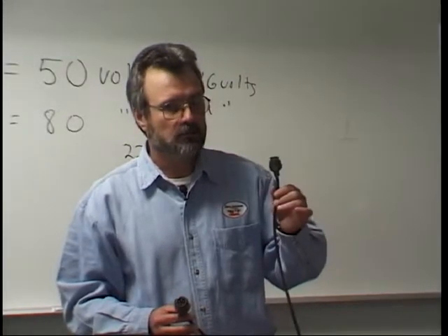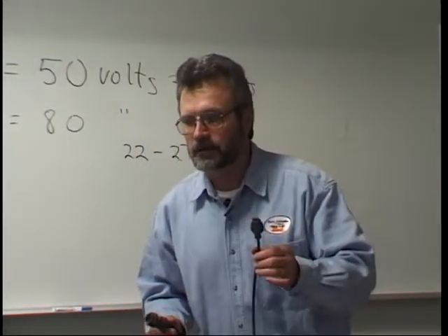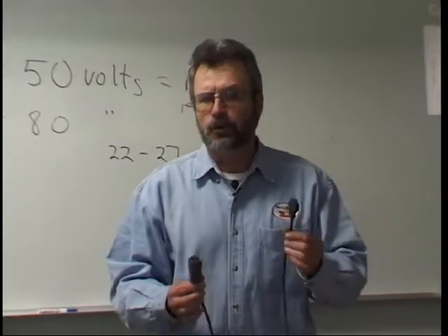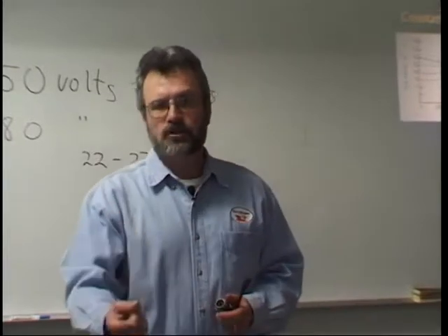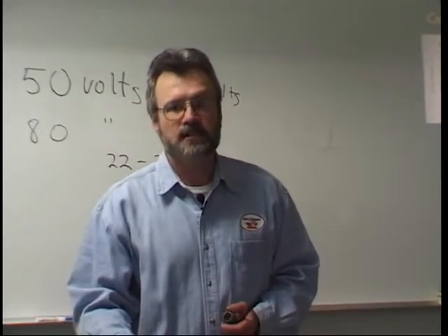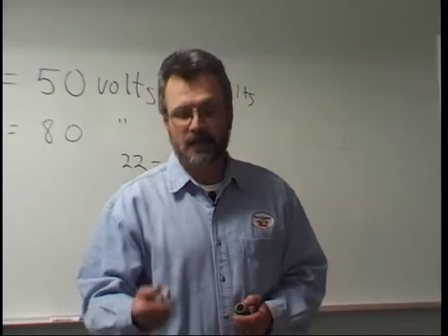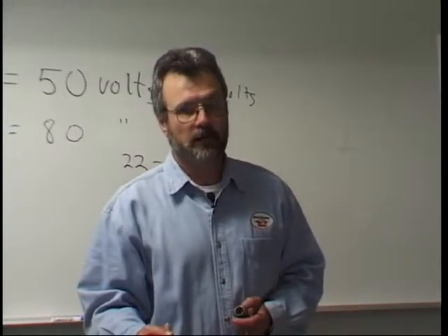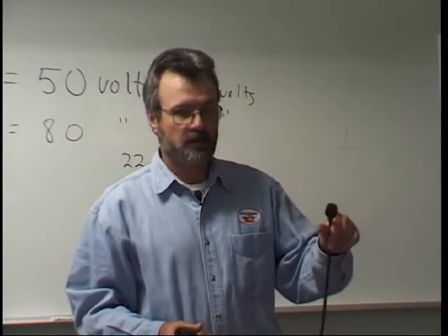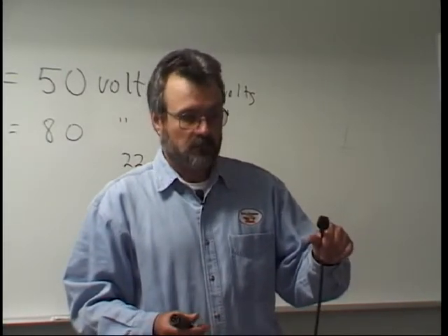And then also, if we don't cover it, if I don't read it out of the book or you don't find it, remember that when you pull the trigger, three things happen. You initiate this solenoid, which makes the gas flow start. You energize the system so that you have welding amperage available, and you kick that motor into gear. Okay? So a lot of things happen when you pull that trigger. And if this thing isn't making good contact, nothing's going to happen.